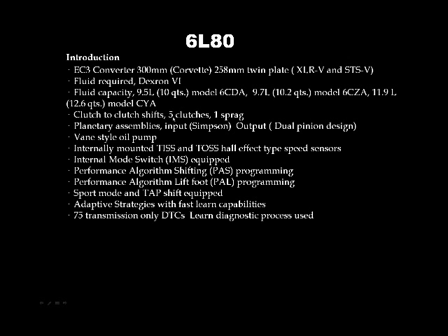Clutch-to-clutch shift transmission, there are 5 multiple disc clutches and 1 sprag. What's that mean to us in simple terms? That means we've got to be very careful in making sure that we relearn the adapts in this transmission when we're all said and done with it. Because clutch-to-clutch shifts, as you all know, like on a 604, will get you in trouble if you do not relearn the adapts.